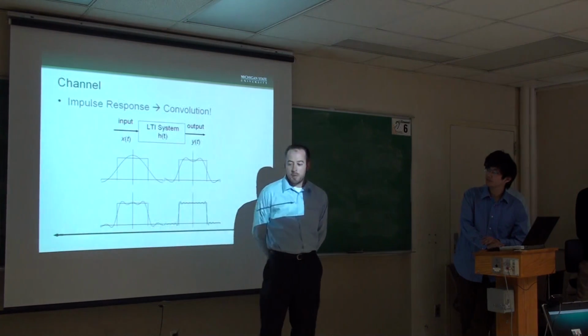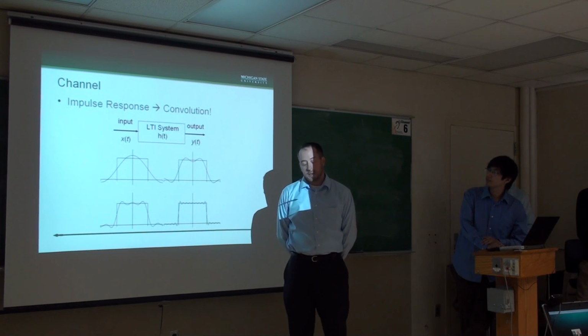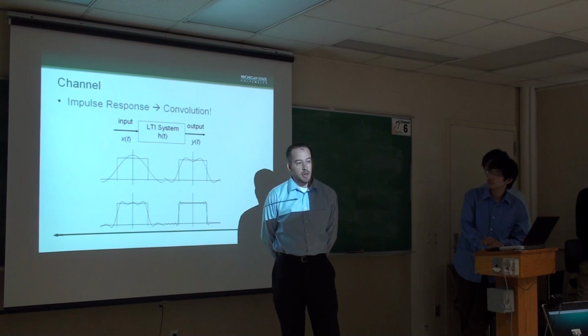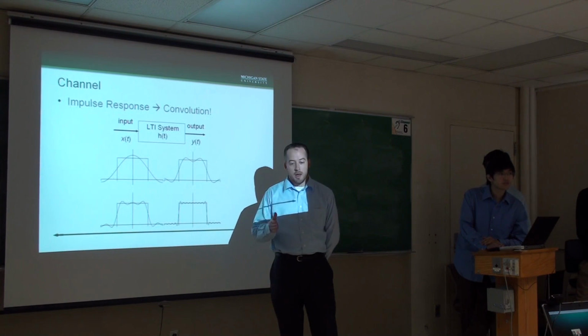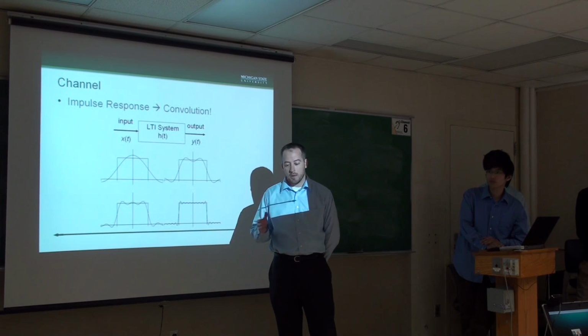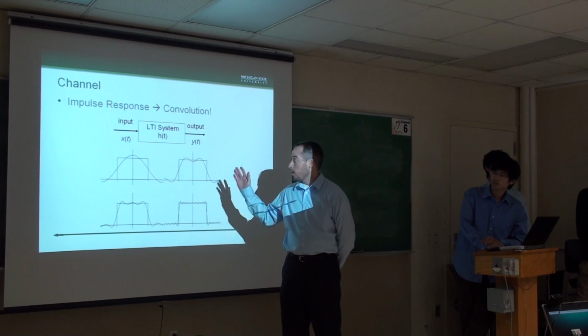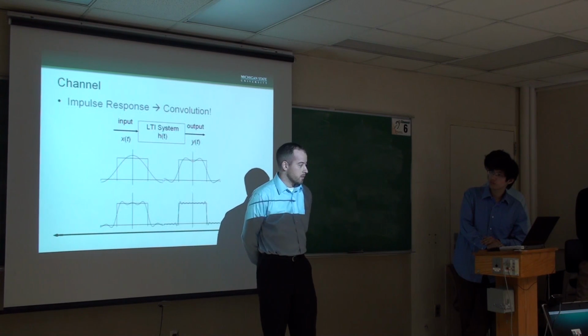So we are going to observe the Nyquist rate, and also we need to learn from the lessons learned from the telephone company. They recognize the bandwidth of twisted pair, and what they observe as their bandwidth is about 4 kilohertz. So we want to be in that range, about 1 kilohertz to 4 kilohertz, and not get all the way up to the megahertz range and have some significant distortion.